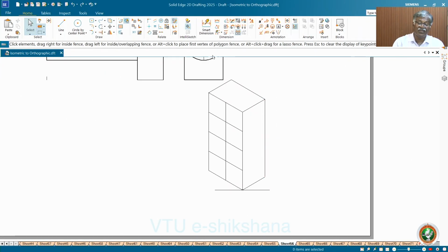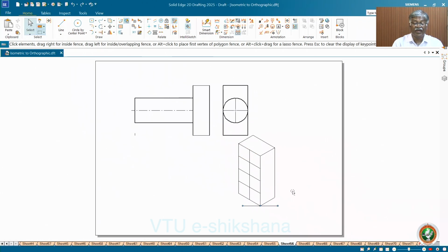Then you will get this. I will identify the center of this, because I have to locate the circle centrally, so that this becomes one end of the cylinder, which is placed exactly at the center of this. So you take 15, 15 and draw 30-degree lines to this, because we want to have a square as the reference, because the box for this circle is a square.